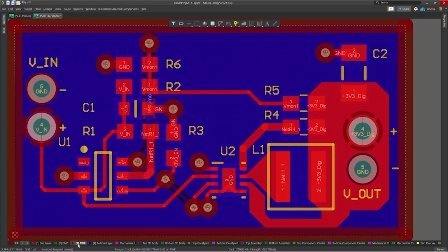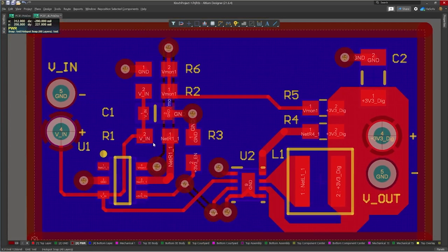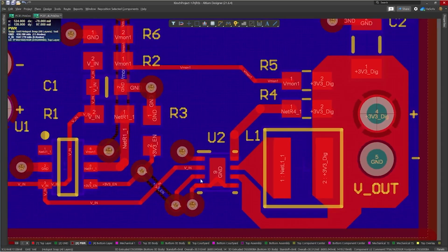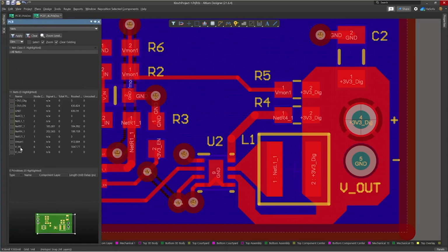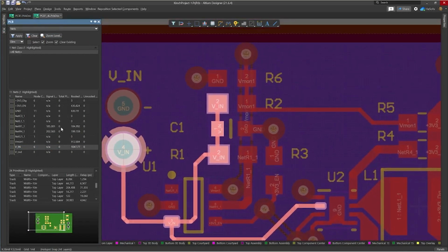This is a full plane, all solid copper on this third layer, this power layer. And those areas cover and provide voltage to all manner of components around it. So I would probably have an area for VIN all around here under my VIN devices, my VIN nets. And here's VIN, that's easy to take a look at.